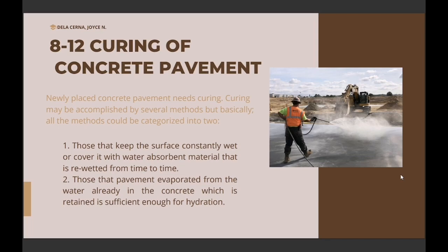Concrete typically takes 24 to 48 hours to dry enough for you to walk or drive on it. However, concrete drying is a continuous and fluid event and usually reaches its full effective strength after about 28 days.